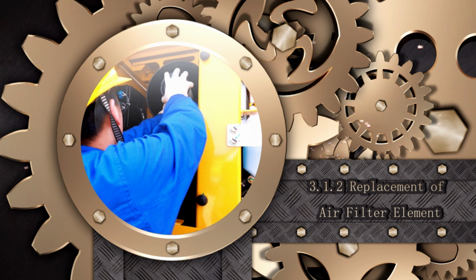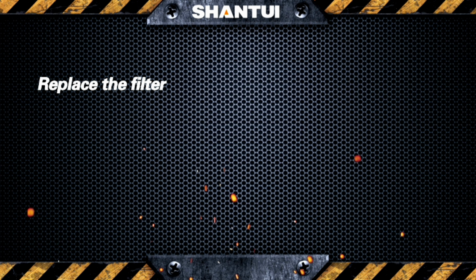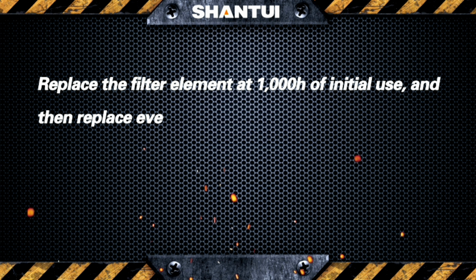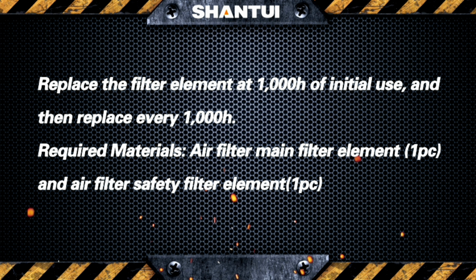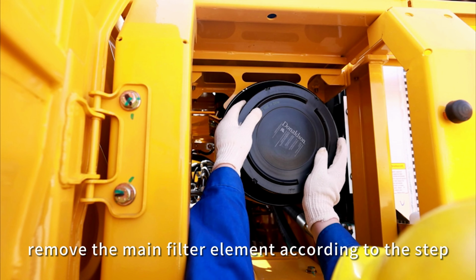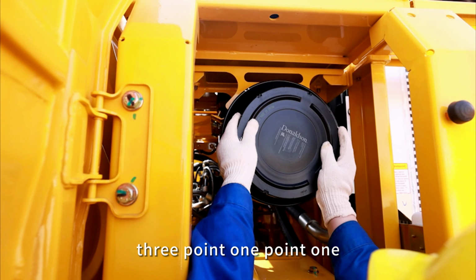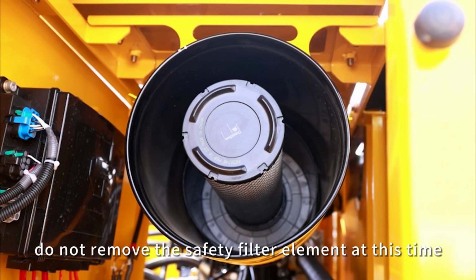Replacement of air filter element. Replace the filter element at 1,000H of initial use, and then replace every 1,000H. Required materials: air filter main filter element, 1 PC, and air filter safety filter element, 1 PC. Remove the main filter element according to step 3.1.1. Notes: do not remove the safety filter element at this time.